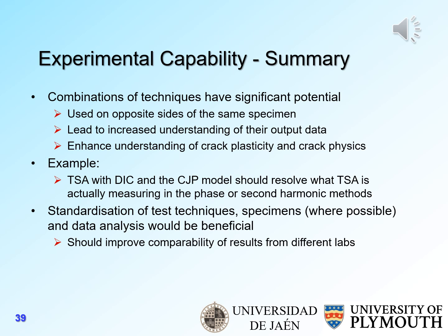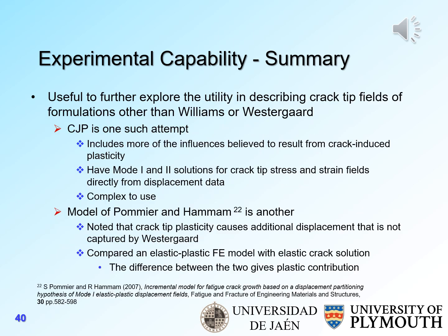Another issue that is important going forwards, I believe, is standardization of test techniques, of specimens where possible, and of data analysis. That would improve comparability of results from different laboratories, and that would be really quite useful. I believe that it is very useful going forwards to further explore the utility in describing crack tip fields of formulations other than the Williams or Westergaard, which seems to be used almost exclusively when people do work on crack tip fields and crack closure.